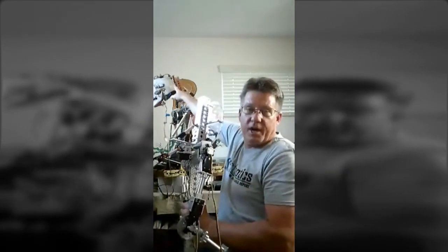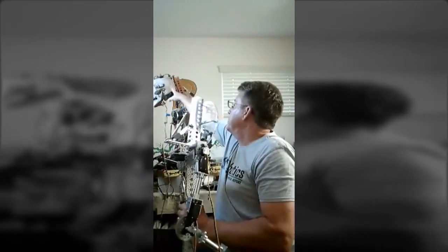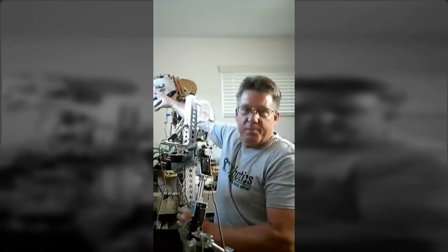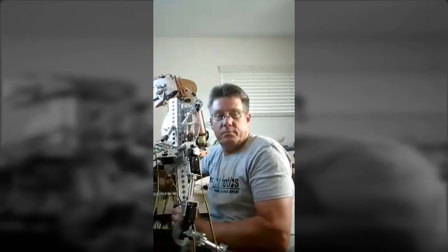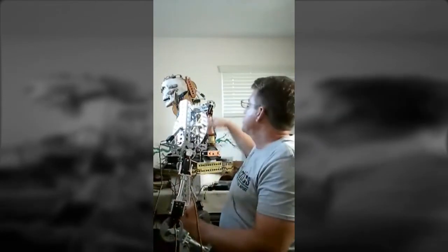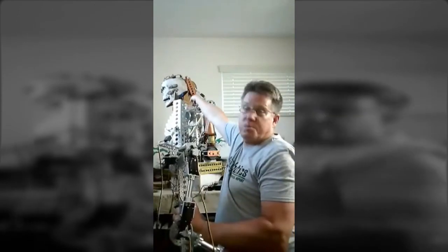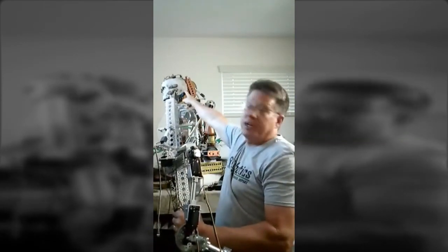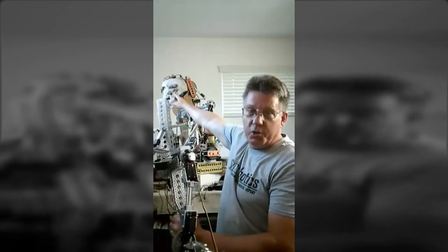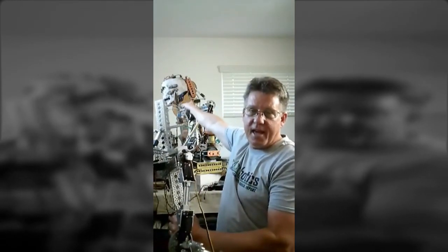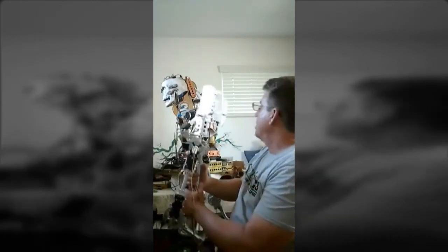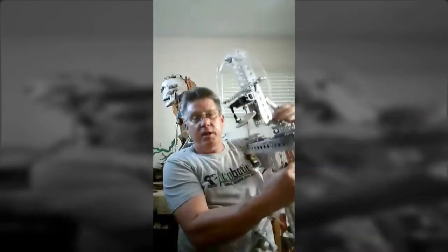You can see how I've got his head mounted on the frame, so all that weight is mounted up on the front end. Get him back there. I even installed a spring back here to help. There was no way I was going to get anything less than a $200 servo to get that nod to work the way I wanted. So that was the first one that I went with the linear actuators on, and it works so well that that's just the way I build them now. So that's what I do for a different version of a 3-axis if I want to use it for a mask.